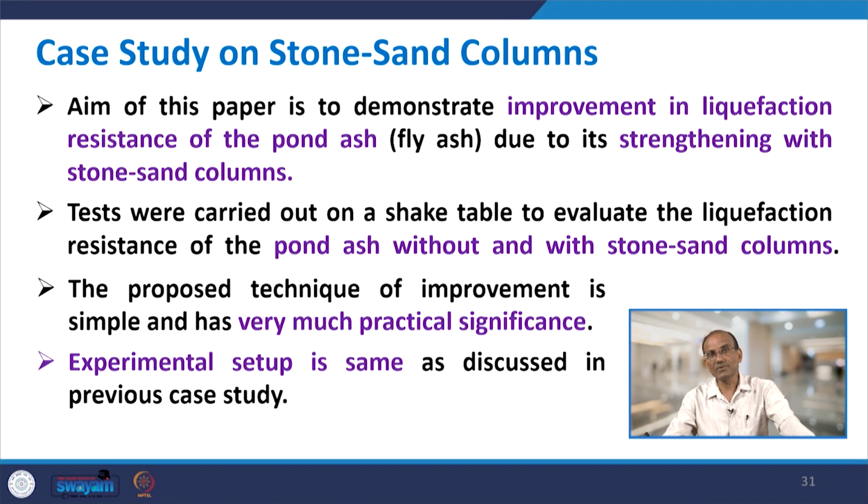So, the challenge was how to improve its soil property, and in fact, we got a live industrial project related to that in the department, which was from the Ampara site. The aim of this paper is to demonstrate improvement in liquefaction resistance of the pond ash, also called fly ash, due to its strengthening with stone sand columns.